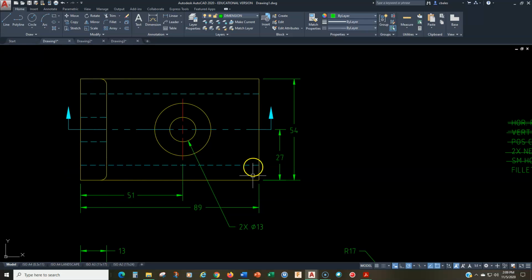So this back edge is important, and from the front edge here. Now you might say, wait a second, isn't the cylinder kind of centered in that? And clearly when I had two 27s in there, you could see that it was. 27 is half of 54. So is there a way to imply or to clearly indicate that the cylinder is located in the middle of this part? Yeah, absolutely. And we do that with the center line or the cutting plane line right there.